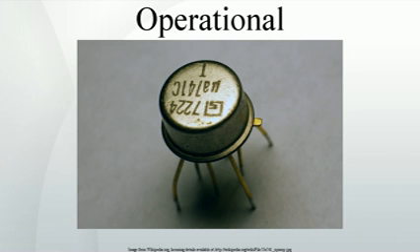A supply current for a typical 741 of about 2 mA agrees with the notion that these two bias currents dominate the quiescent supply current. Transistors Q11 and Q10 form a Widlar current mirror, with quiescent current in Q10, I10, such that ln(I11/I10) equals I10 × 5K/28 mV, where 5K represents the emitter resistor of Q10, and 28 mV is Vt, the thermal voltage at room temperature. In this case I10 is 20 μA.